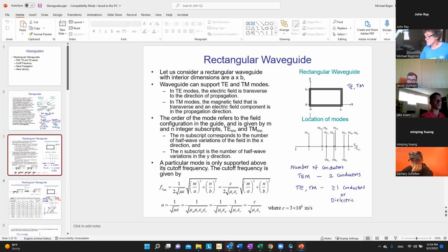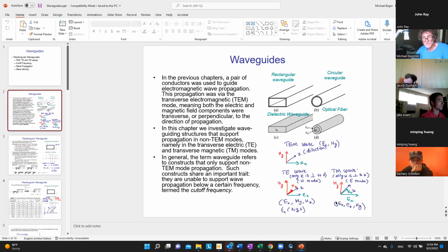That's important. Another thing about this, let me just move back for 1 second because you should know this. With these guides, you can put a little juncture, or you can bend them. You can't bend them very much. And there's what's called the maximum rate of curvature, because if you exceed that, then the wave that's going down there will reflect back. It will not keep going. So there's all sorts of limitations on the amounts of bends you can do and other things. And we'll get into that.